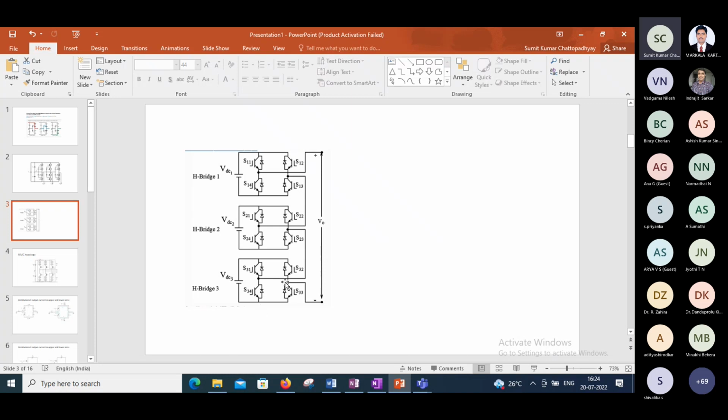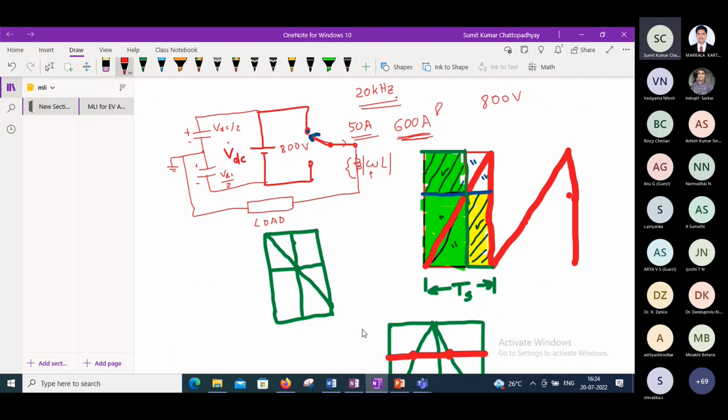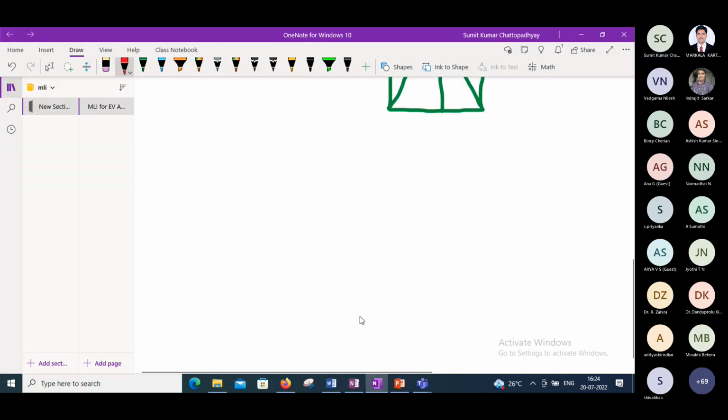So other than optimizing the switching loss and conduction loss, also we can say that if one of the battery packs fails, we can permanently bypass it. So it adds to fault tolerance. Moreover, one more very important aspect now I wish to discuss is the losses in the filter.